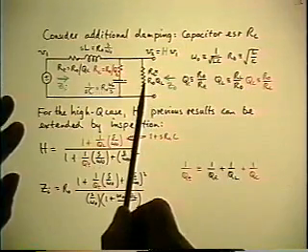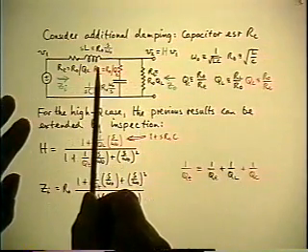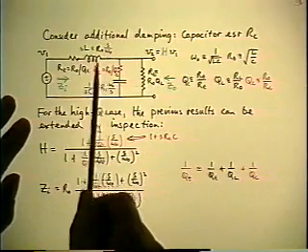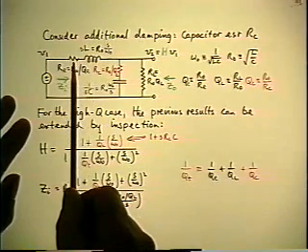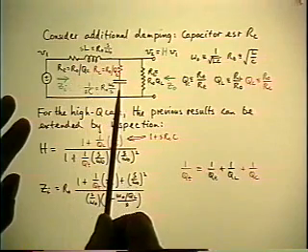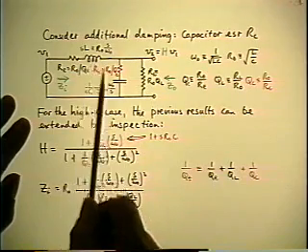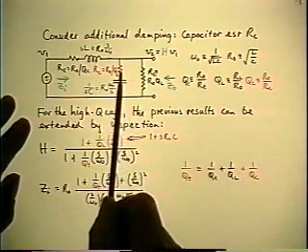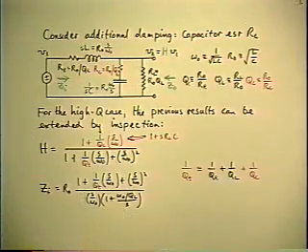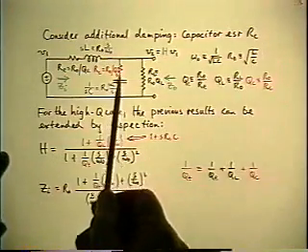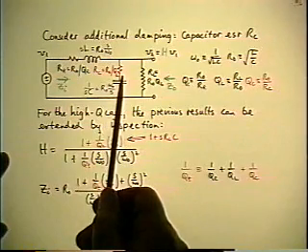Go to the other extreme. As frequency approaches infinity, inductive reactance increases, the RE drops out. The capacitive reactance decreases. The RL drops out. So you're left basically with a pure LC filter in the absence of the RC. And that's what gives you the double slope, the LC filter, because you get an S from both of those elements towards infinite frequency. So the question remains, if you put the RC in there, does that make any difference to the infinite frequency slope?